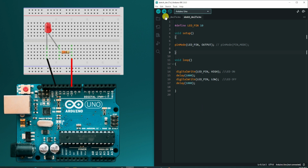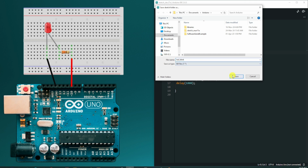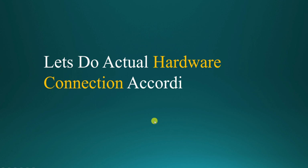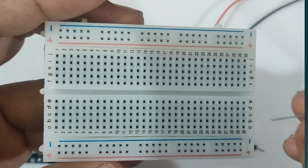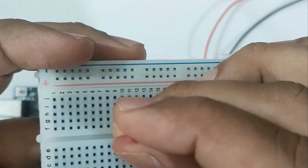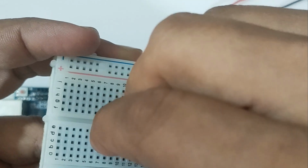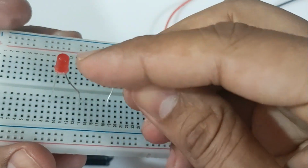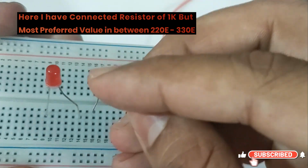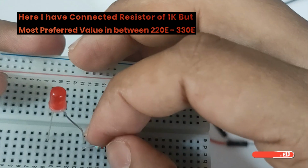Before flashing, we'll first save this code. It will take time to save. Let's do the actual hardware configuration by connecting all components. Let's start the hardware connection. First we will connect the LED on the breadboard. After that we will connect one terminal of the resistor to the anode of the LED, and the other terminal will be connected to digital pin 10 through a jumper wire.